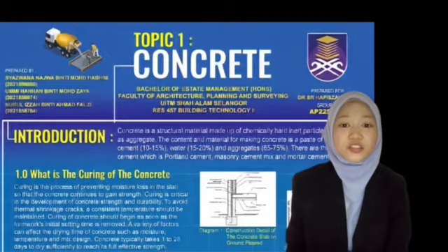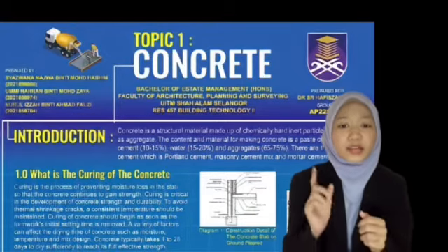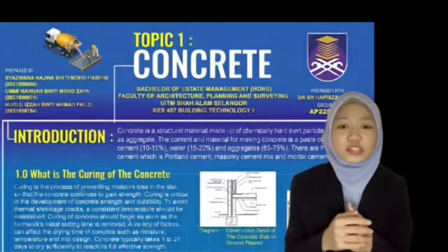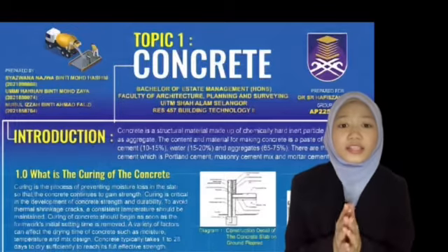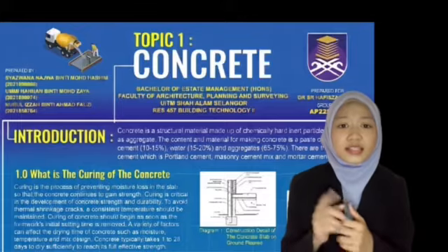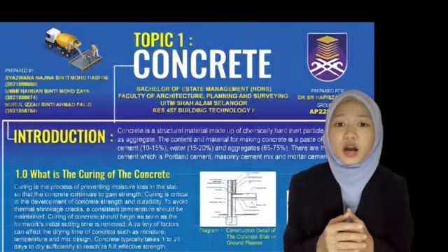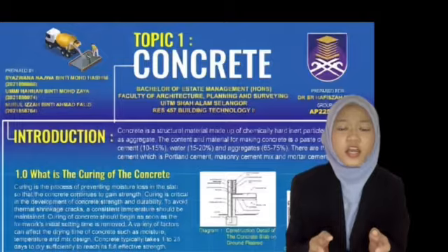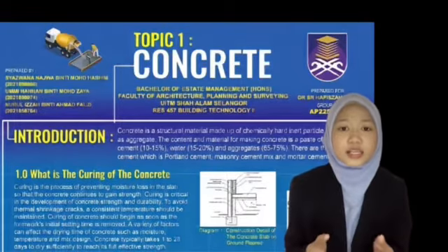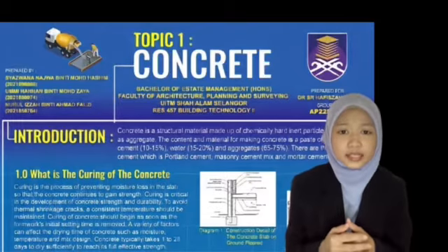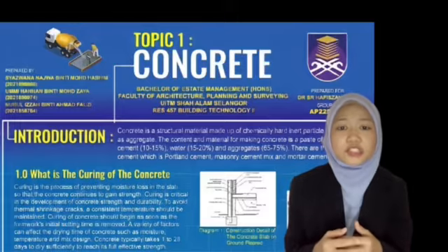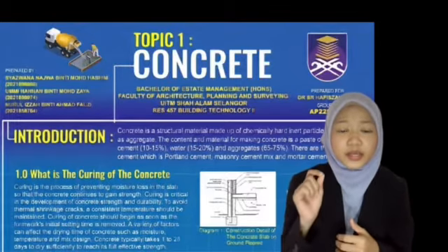Okay, now what is curing concrete? Curing is the process of preventing moisture loss in the slab so that the concrete continues to gain strength. Concrete requires moisture retention and desired temperature conditions. A consistent temperature should be maintained throughout the depth of the concrete section to avoid thermal shrinkage crack. In other words, curing is the process of protecting concrete from internal moisture loss while also accelerating the hydration reaction to achieve the required strength in a shorter period of time.